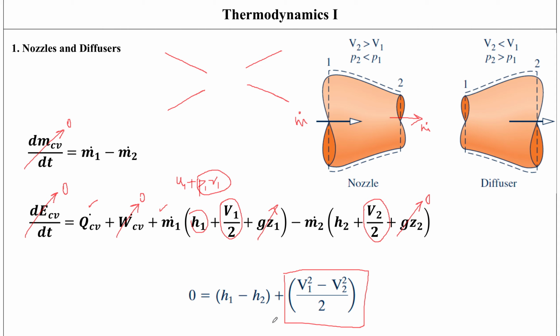So this is how you work out nozzles and how they're based on control volumes. Why is it a control volume? Because mass is also being exchanged between the system and the surroundings, besides just energy. So if you want to practice this, I would recommend that you go to Shapiro's book and look at example 4.3, which is about calculating the exit area of a steam nozzle. So you will have a good idea once you apply these equations onto an example problem.